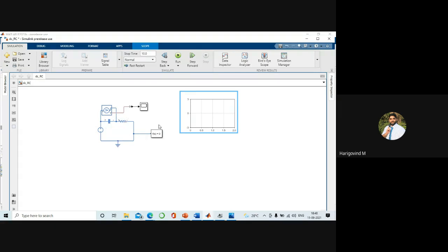And as I said earlier, at the end, Simulink only knows how to solve differential equations, and these are physical systems. So there should be something which can translate the system to differential equations. Simulink is an equation-based solution module. So just give the solver configuration. Every time you use a Simscape model, you have to give the solver configuration, because if you don't give it, there will be an error that these things are not defined. I'll show you what the error is. We can run this.